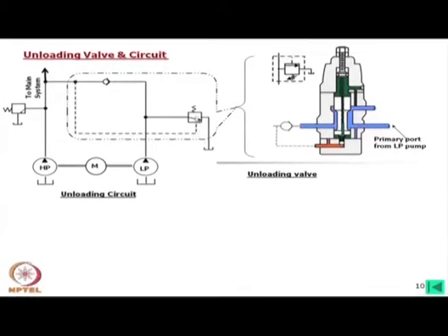Again, this pressure is not sufficient to open this one. If it is not sufficient to open this, then this will remain closed, but if there is a high pressure, this will open and then oil will go to this, is it not? Let us consider that the pressure setting here is 10 megapascals and the system pressure is more than that.